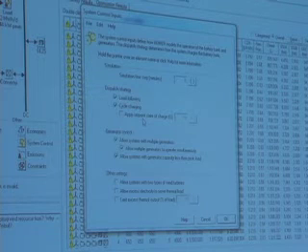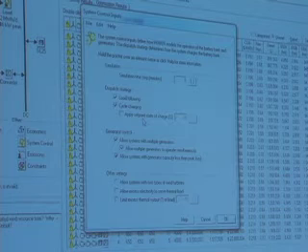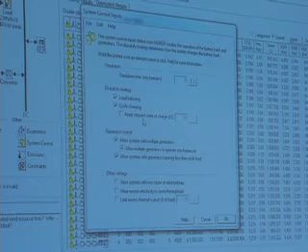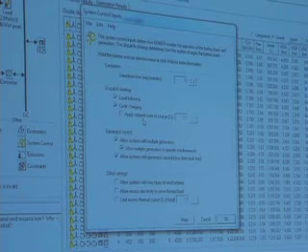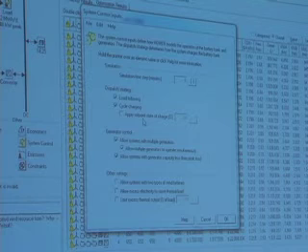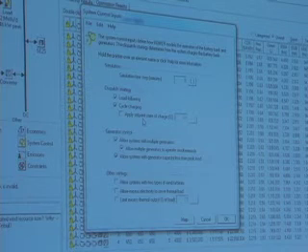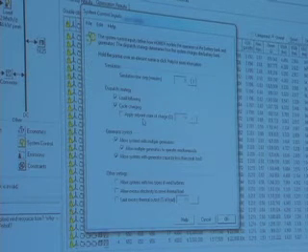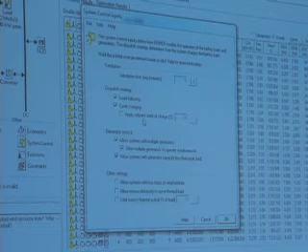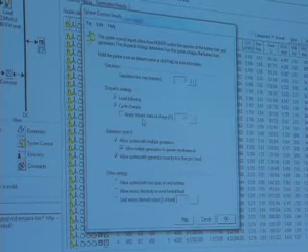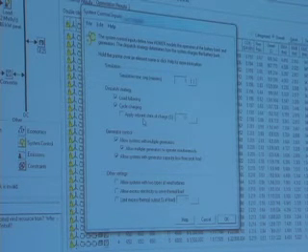Now, if you charge the batteries too much, you may get to a situation where the batteries are full and you've got this excess wind energy, and it has to go to the dump load. It has to be either thrown away or go to a low value secondary load. So it's not always optimal to charge the batteries with the generator. But it can be. So that's what cycle charging is for.